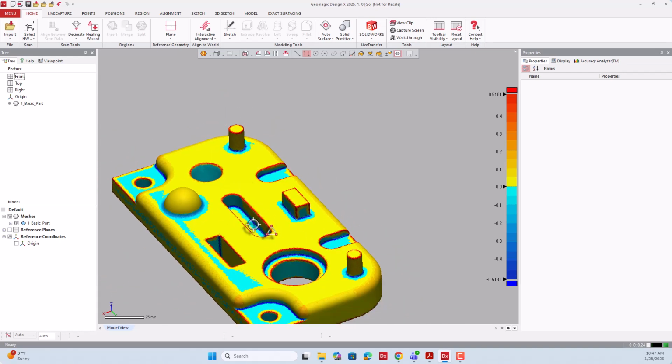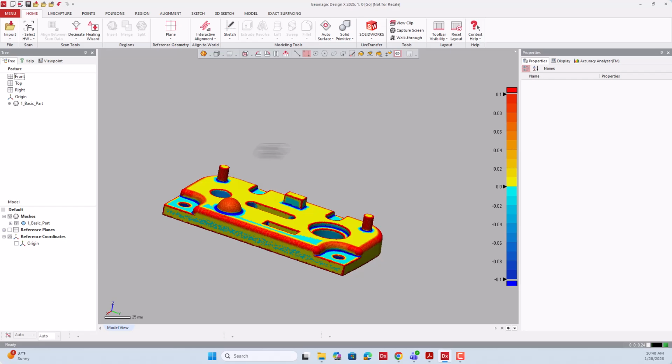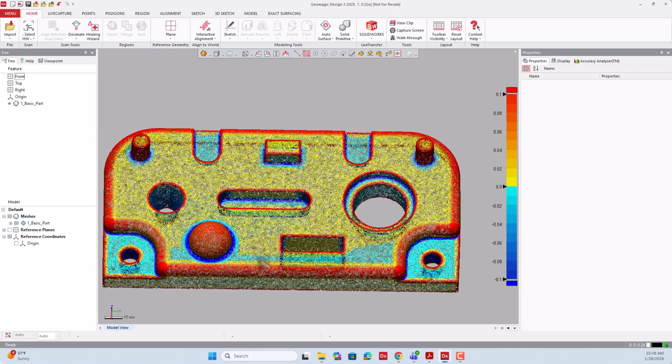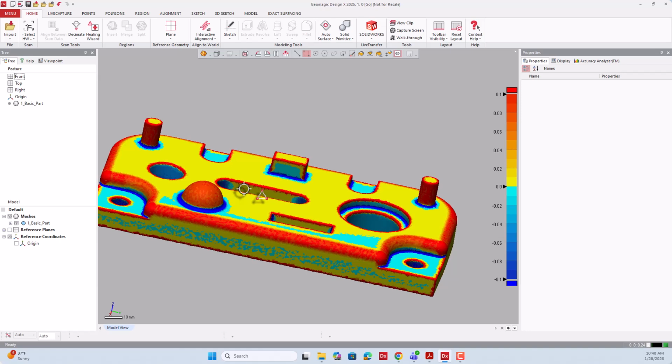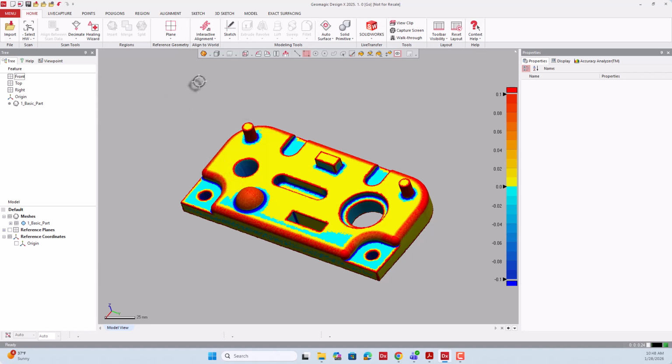So this is how you can plot the curvature, and it has a scale here. You can double click on that number and change it accordingly. If I'm changing it to 0.1 here and then clicking again on screen, it will make it appear a bit darker. So here we can take a look and see how the faces of the polygons are changing by viewing the curvature.